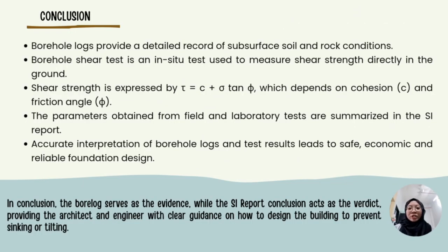So for the conclusion, borehole logs provide a detailed record of subsurface soil and rock conditions. The borehole shear test is an in situ test used to measure shear strength directly in the ground. Shear strength is expressed by the formula, which depends on cohesion and friction angle. The parameters obtained from field and laboratory tests are summarized in the SI report. Accurate interpretation of borehole logs and test results leads to safe, economical, and reliable foundation design.